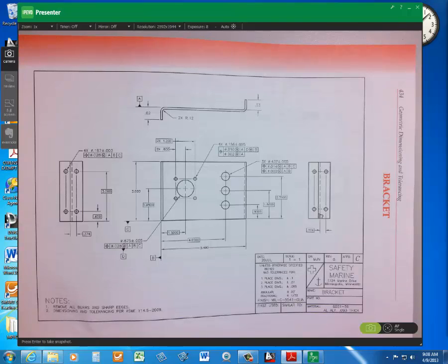Okay. Now D, completely described. This is a long description. So you basically just start off saying the information, kind of what you have. It's a composite positional tolerance using rectangular coordinate dimensioning. That's the first thing.